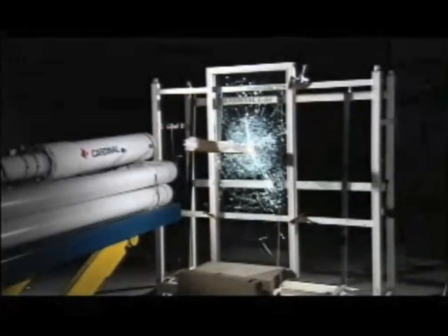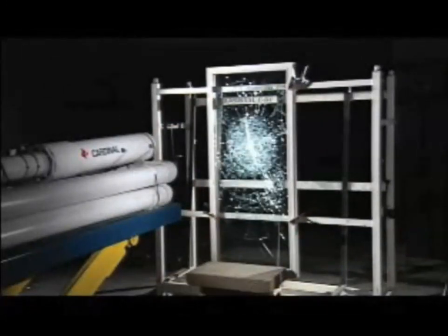If the building envelope is breached through a broken window, wind may enter the building, causing an increase in pressure that could lift the roof and push the walls outward. Laminated glass helps to preserve the building envelope, keeping wind and other elements outside. During hurricanes and windstorms, windborne debris is common. So Cardinal tests finished window systems with laminated glass to verify that they stay intact and resist penetration.